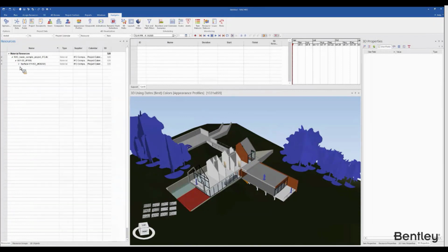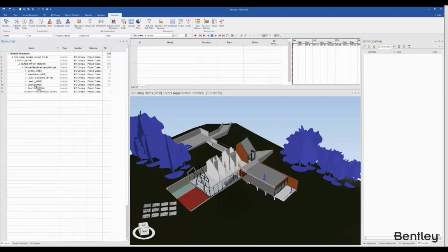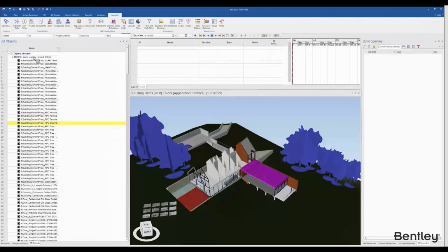So just like Revit, IFC has its own way of creating this tree, and you can define that in your IFC writing software. But this, you don't want to change. Just like how we cannot edit the 3D object tree in any other file format, here this has a one-to-one relationship to any 3D objects. So you don't want to change the sequencing or the grouping of those resources. You want to use the same resources.